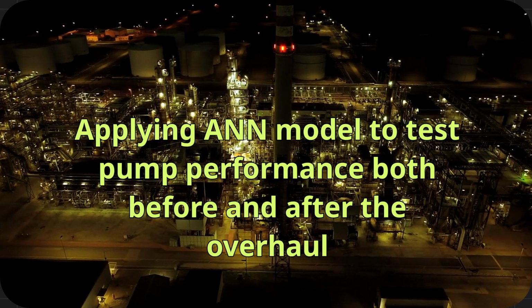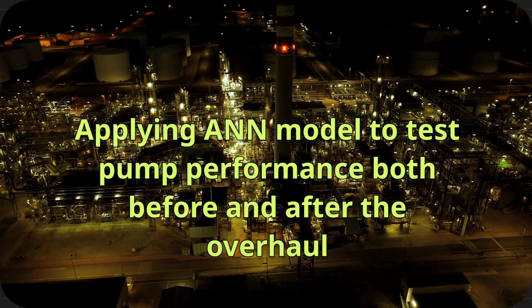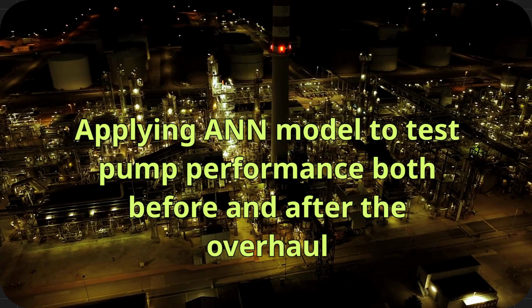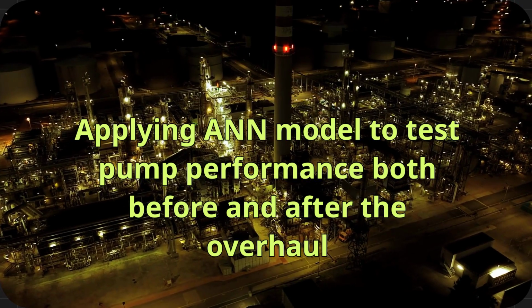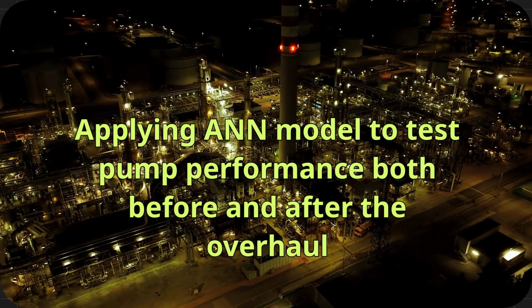In contrast, after the overhaul, there is a noticeable and consistent rise in the slope of the error curve. This steep increase persists over time, even though the pump's operating hours are comparable to those within the training dataset. Such behavior strongly indicates an abnormal condition or malfunction occurring immediately after the overhaul.